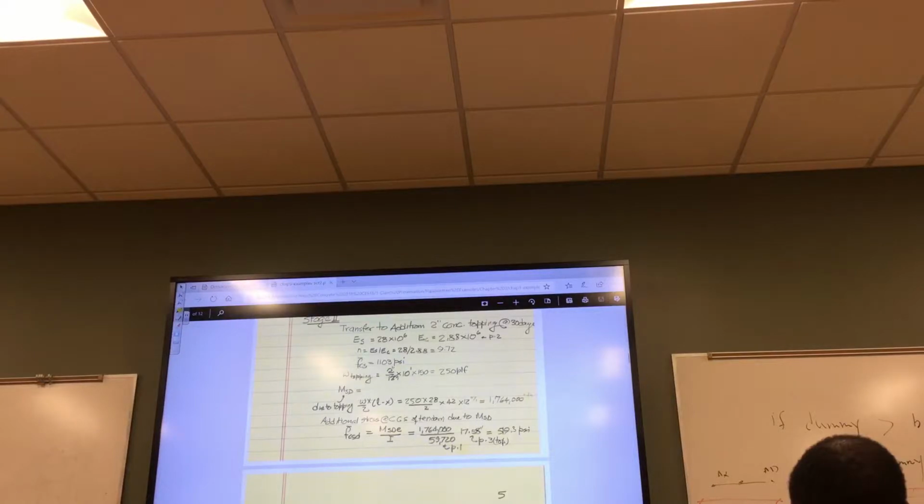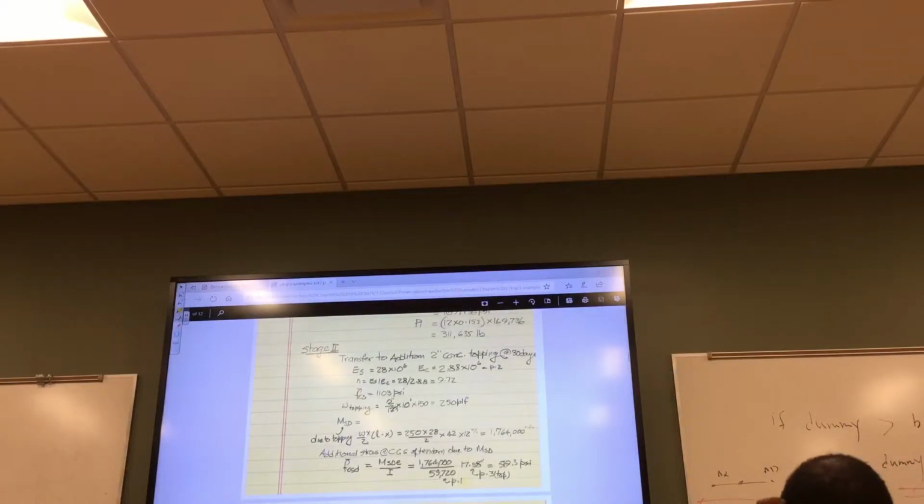So once you calculate that, then the additional stress is 519 PSI at the critical location. In this case, the critical location is not at the midspan, it is at 0.4 L, so we had all that discussed last time, right? So in that case, the moment is not WL squared over 8, it is this little more complicated looking expression for moment calculation, right?